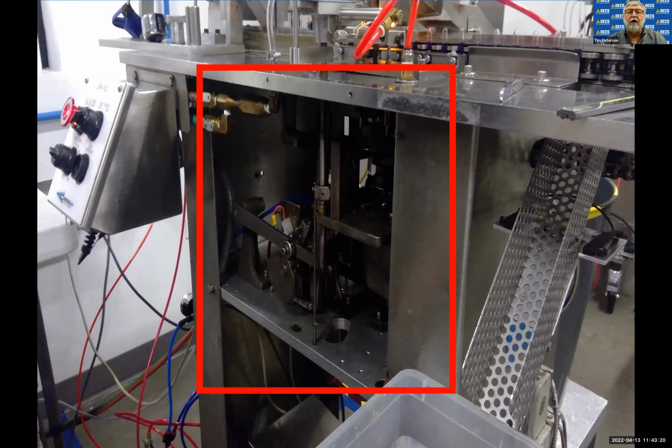So look at machine guarding as one of those physical hazards and really look at it as, am I allowing that employee to create that access point, or if I created a way to prevent them from getting to that point of operation? And there's a lot of different ways to accomplish it. It just needs a little discussion once in a while.